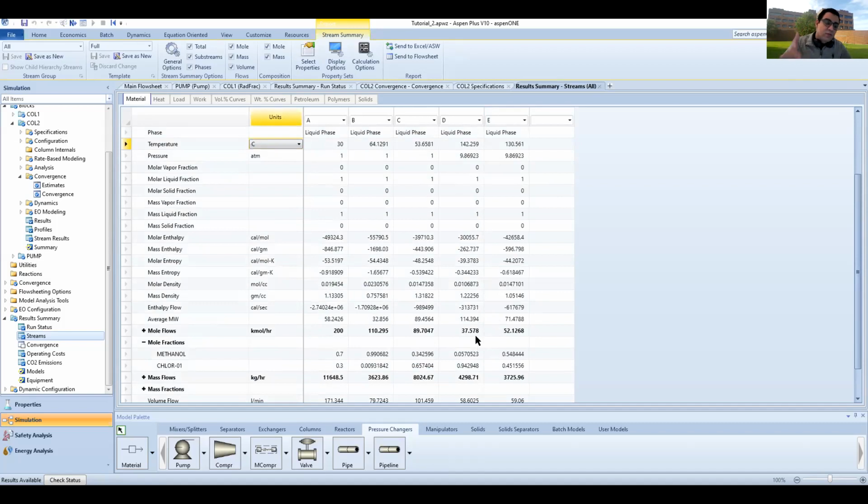Okay. So mole fraction of the azeotrope is what we expected. If you recall from the first part, we said that the azeotrope occurs at about 0.52. Here we're getting about 0.55, so it's fine, reasonable enough. So now I'm going to connect the recycle stream to the first column.